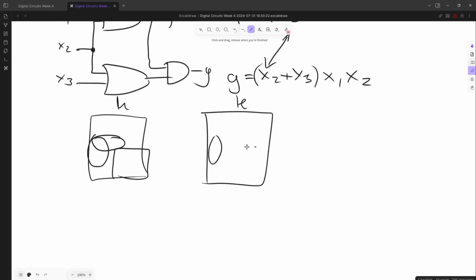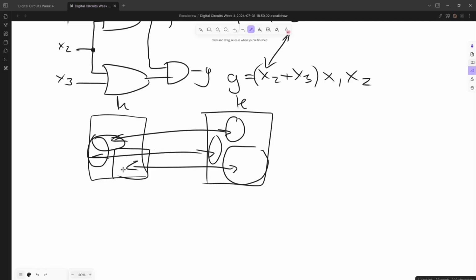And it's very similar to h, except it kind of looks like this, right? You'll notice that you have a common group here, but you have an uncommon group here. You could implement both h and k at that first step with these two groups, and then for h and k, their individual differences, you just have to add another AND gate, or change to an OR gate, or whatever you need, and that'll be more than enough. Actually, sorry, not more than enough. It'll be most optimized for both of those functions without having to create one for h, create one for k.